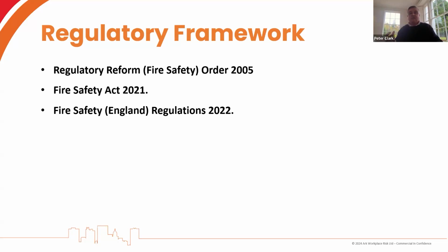So, asking that assessor to look at that, to look at fire doors as well. So look at the doors, particularly in multi-occupied residential buildings, that flat front door is an incredible piece of passive fire safety, incredibly important. And again, go back to Grenfell, look at what went wrong and learn from those things that went wrong. All of those doors that didn't have self-closers on them, all those doors that had been replaced with UPVC, which would never hold back smoke and flame. We didn't stand a chance, but now we do. The Fire Safety Act 2021, your risk assessments now should be looking at those sorts of things.